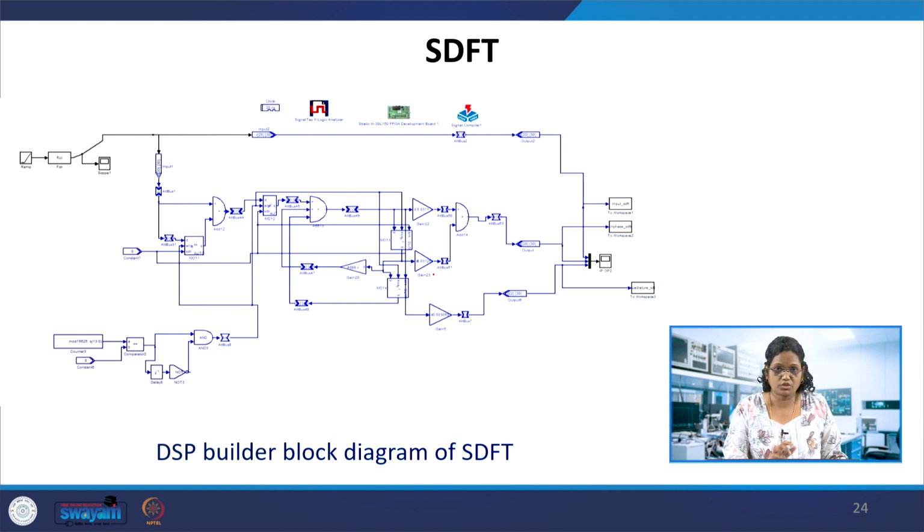So those tools need to be installed along with MATLAB Simulink. By verifying the MATLAB version you use, compatibility can be checked for what is required for these DSP Builder blocks to be made. Once you have this in Simulink, you will get the Altera block set as a separate toolbox. The Altera block set will contain adders, delays, and input blocks, input output pins, all of which are very suitable for programming the FPGA, or getting the HDL code.